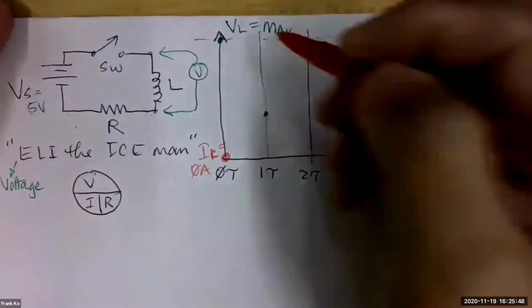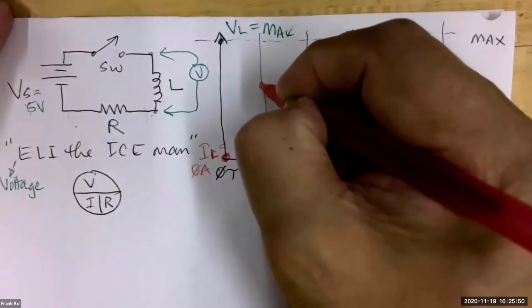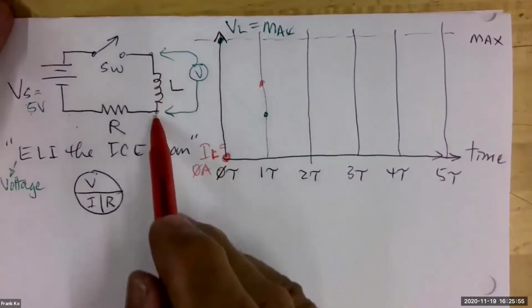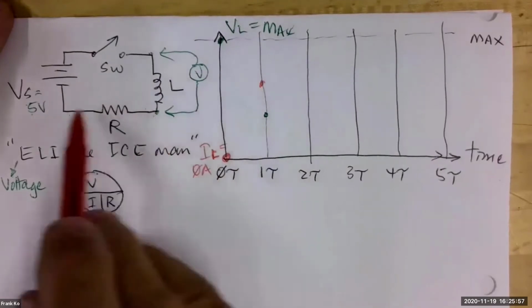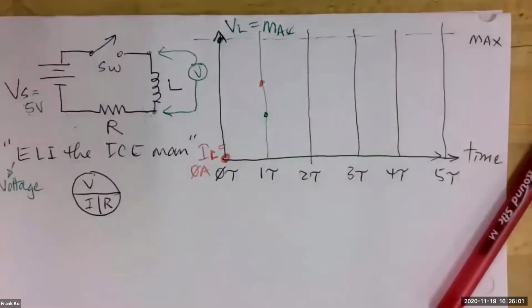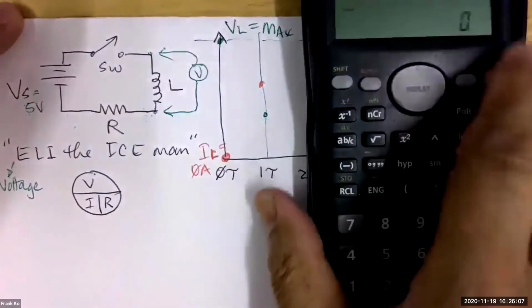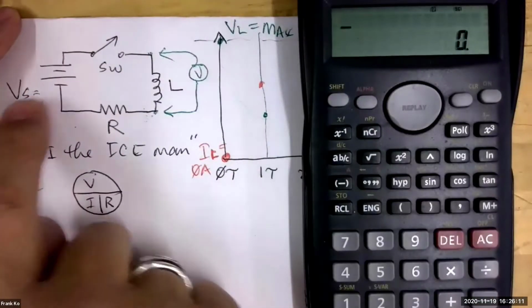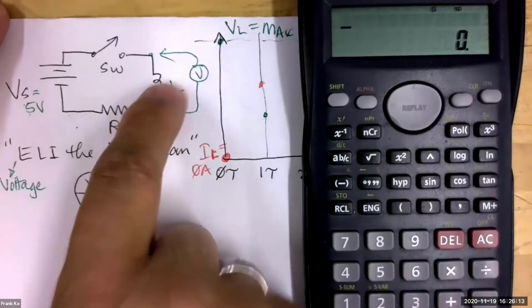And the current, conversely, will go up 63.2%. Because as the voltage drops across this guy, you will have some voltage here. Let's go ahead and do some quick math on your calculators and see what our voltages will be after 1 time constant, okay? This is very easy to do. We have a 5 volt source, yes? And 5 volts is what we're starting with here.